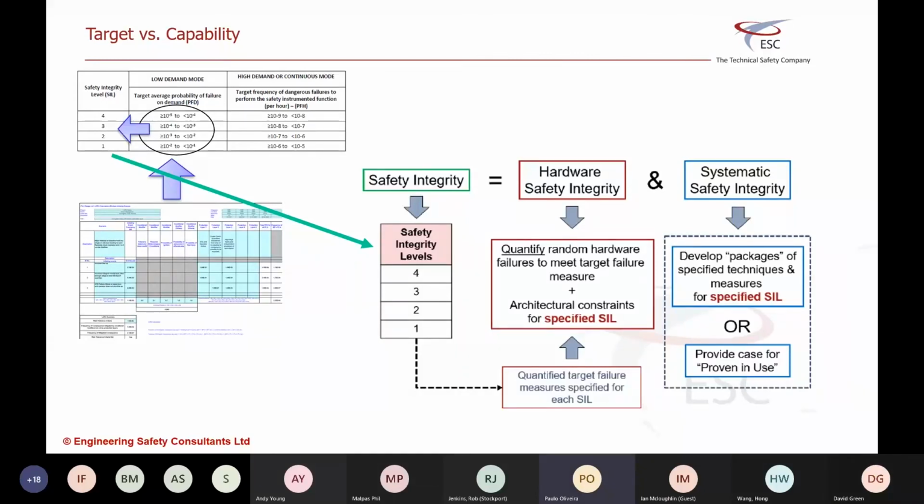Your LOPA gives you a number to open the door to the non-numerical aspect of the standard, which is in reality the reason why the standard exists, because we've done reliability calculations for many decades. What we haven't done very well is making sure that other errors don't go and basically undermine that reliability, availability, and integrity calculation that we feel we need to do.